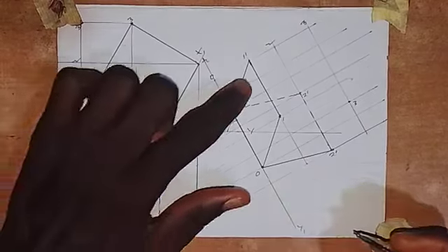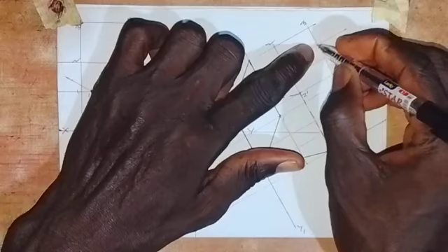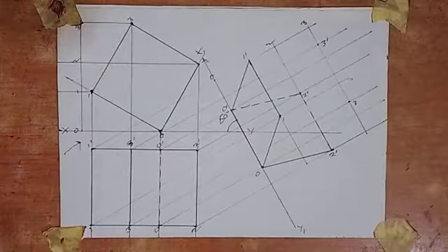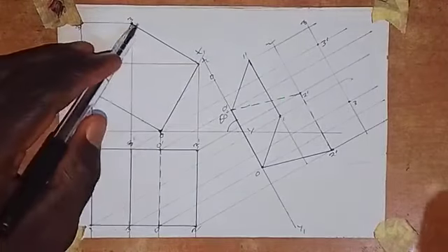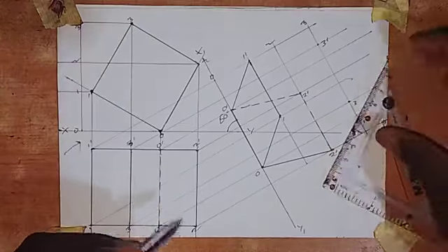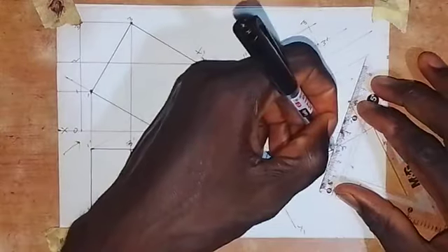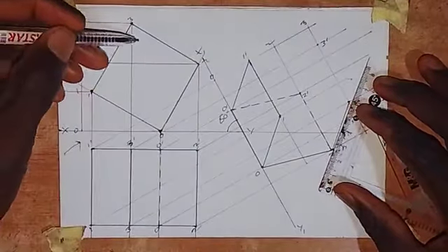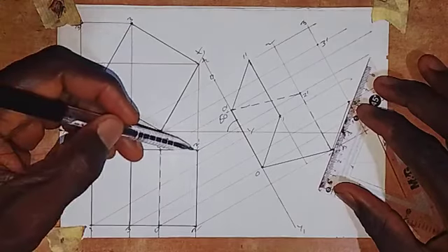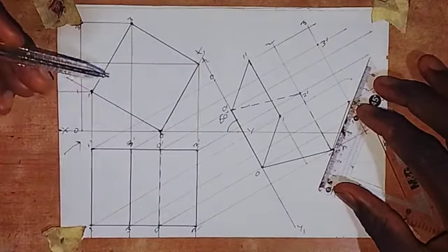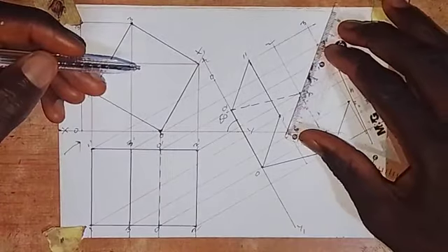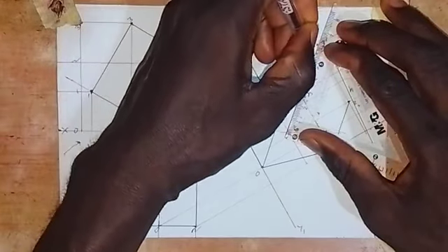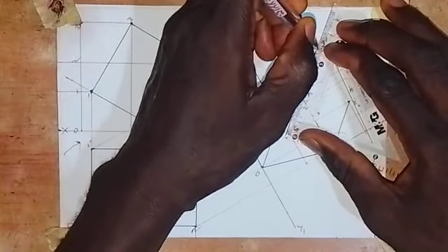So let's locate 3 prime. Go on this line 3. We have this point. This is where we have 3 prime. In this case now, I can see this line, so I'm going to make it a thick line. We join this together as a thick line like this. Then this line at 2 prime 3 prime is to be hidden from us. We can't see it. So make it a short dashes line also like this.